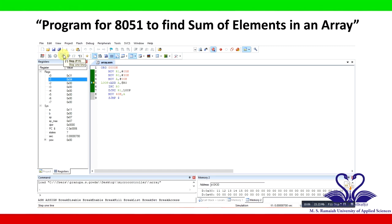ADD A, @R0. R1 is now loaded with 04 because this DJNZ step says that R1 value will be decremented by 1. If it is not 0, it goes back to the loop. Now this looping operation will be executed. Initially A was having 11. Now @R0 means 31. In 31 memory location 12 is there. So 12 plus 11 will be added and the result is 23, which will be stored in accumulator.